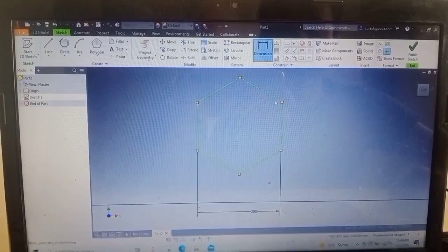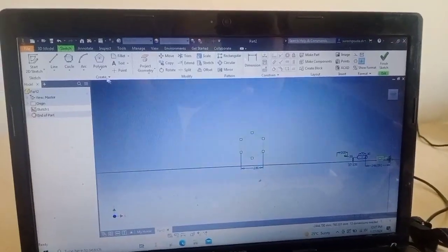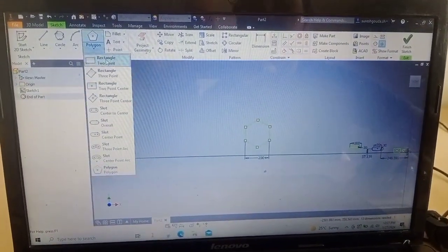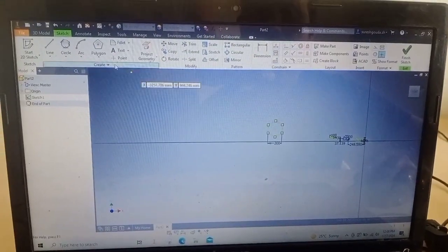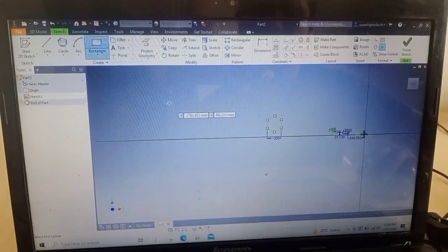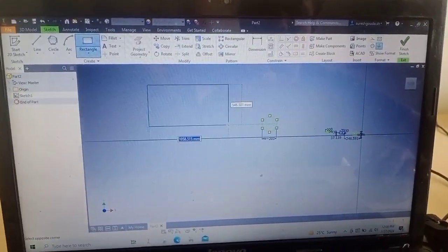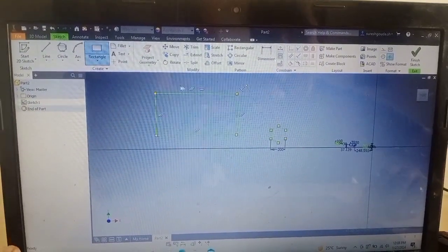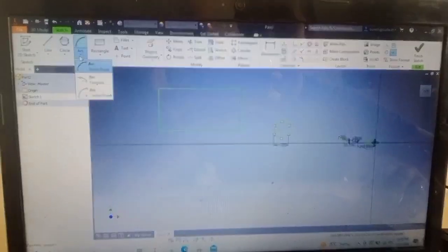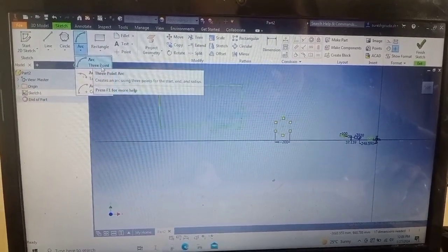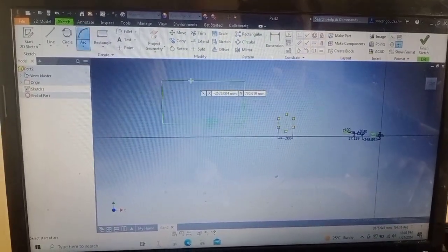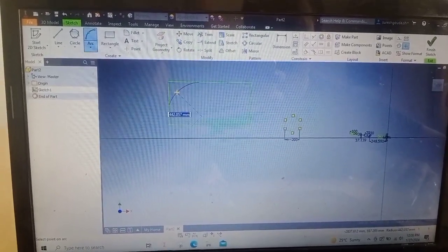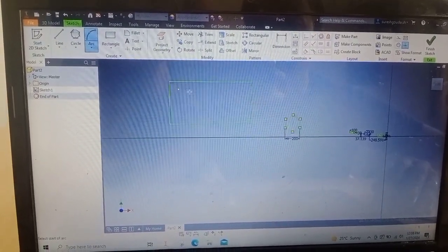it will resize. Now I am going to explain arc command. Okay, and we already learned how to draw rectangle. So I selected the rectangle here, and then I am drawing this, and then press escape to exit out of that command. Okay, now I am going to 3-point arc. So I selected that. This is first point, this is second point, and this is third point.